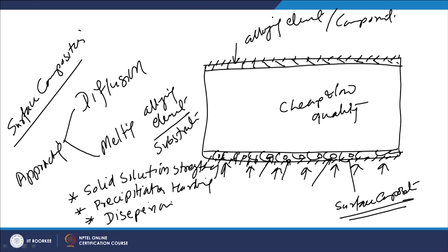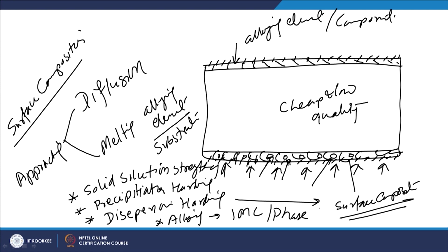So, dispersion hardening is especially utilized when surface composites are made, and sometimes the alloying elements are introduced primarily to achieve the required intermetallic compounds or phases at the surface and near surface layers after subsequent heat treatment. Like phase modification is used in the case of carburizing, where we can get high carbon martensite, while iron nitrides are formed in the case of nitriding.